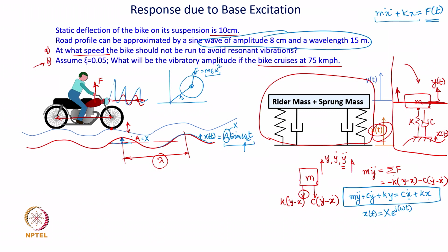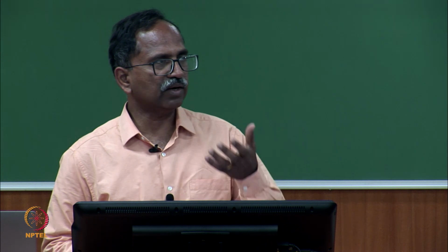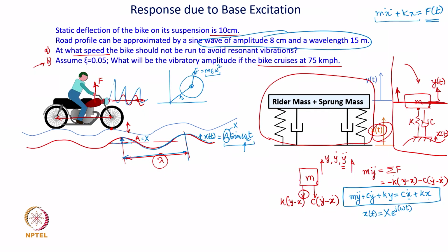So, when the vehicle moves, it experiences maximum amplitude harmonically. This is how it happens. The tire will be moved up and down harmonically with this profile. So, this is our assumed input, just like we defined f of t as f naught e to the power j omega t. The way we defined an external excitation force, this is an external displacement excitation to the system, base excitation.